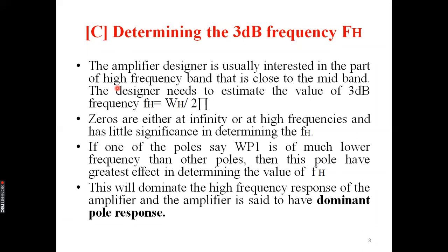So it is not target achieving, whereas design is target achieving. Analysis means we will just monitor the performance of the product, and we will come up with some numerical quantities, some performance specifications or performance values. So here also we are trying to determine the cutoff frequency of an amplifier. The cutoff frequency is specifically called the 3 dB cutoff frequency because 3 dB means it is 0.707 of your maximum gain in dimensionless quantity.